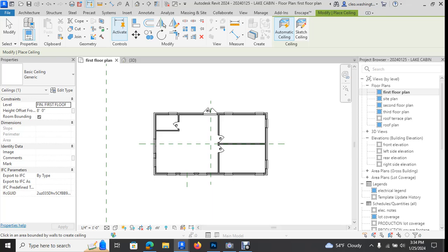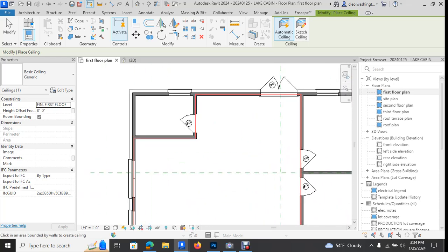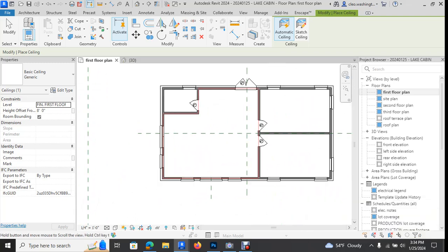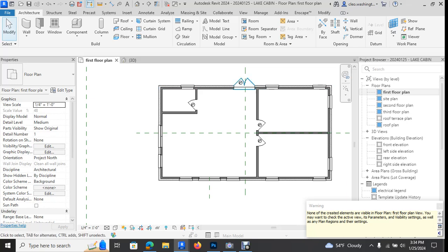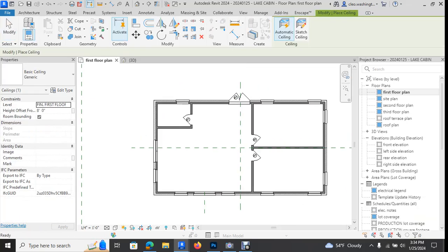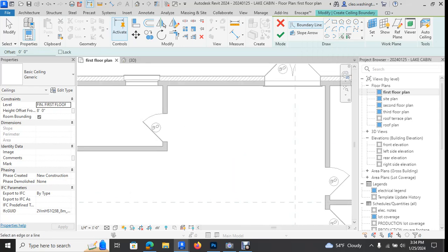Okay. And you can do automatic ceiling, but let's try it. You'd come in and you'd have a ceiling in this room, ceiling in that room, ceiling in that room. It's not creating it because a lot of times you have trouble with ceilings. So let's go back to ceiling, and you want to click sketch ceiling, right? And you want to go back to that same pick lines command, the same thing that we utilized when we put the floor in. Okay.